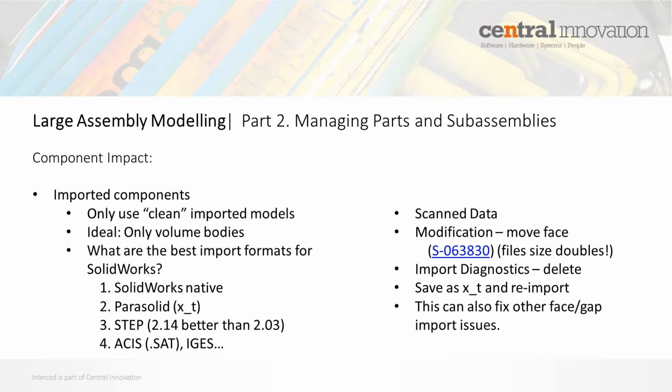Scan data can be imported through Scan to 3D. Sometimes people bring in point cloud data and that sort of thing. Ideally, you really want to limit the amount of that data you have in large assemblies, simply because it tends to be a little bit messy to clean up.